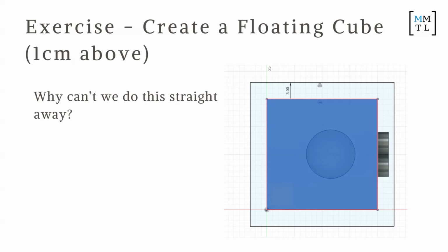Then go back to your extrude function. Going 3 is one layer. Now you want to select also the profile, so remember to use shift to move around. There we go. We're going to select that one, and also the middle hole. If you're done with the task, just take a look at the construct options. They're just useful to have at the back of your mind, particularly when you're designing stuff. Just think about when you'd actually use very different types of constructs.